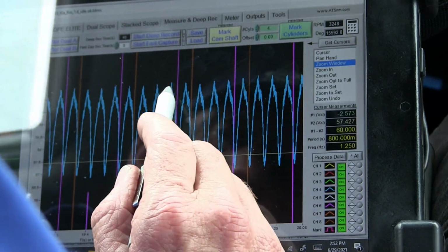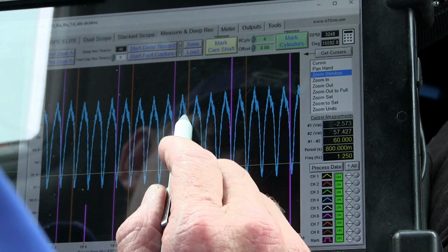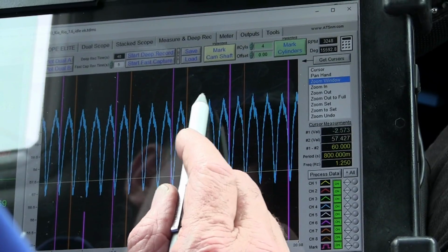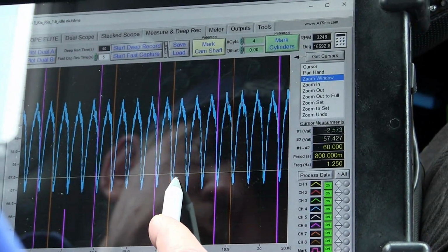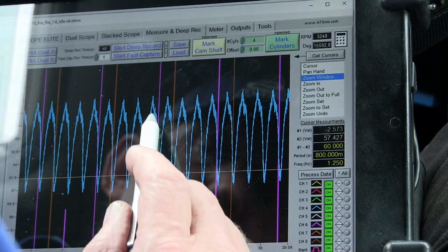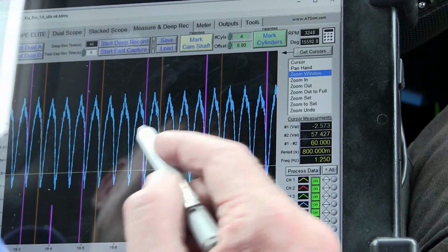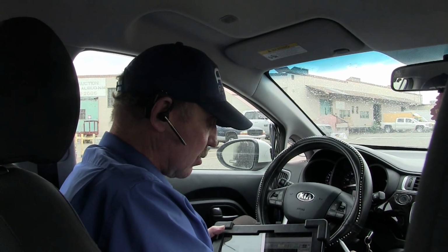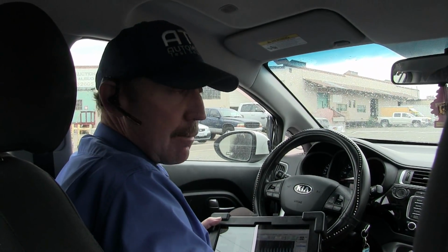Now the pressure is up here, and every time the injector opens I drop, and then the injector opened and I drop. These are injectors, and you can see that on each one of these where the injector opened, the injector fires, it dropped the fuel pressure. Well, that's because it's restricted, and now we've proved it's restricted. We've proved it because the pump didn't change its speed, and the pump would have to change its speed unless it's restricted. So this is showing me I've got a restriction, and then I'm going to prove it with an amp clamp.